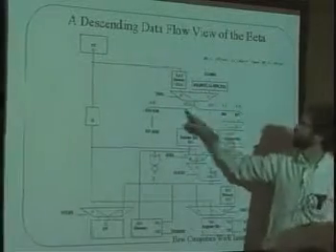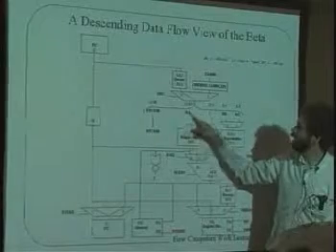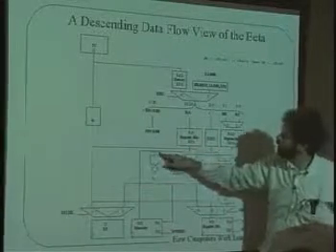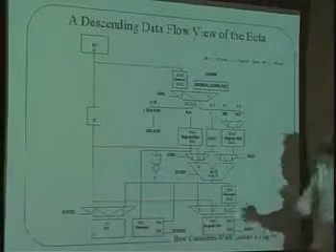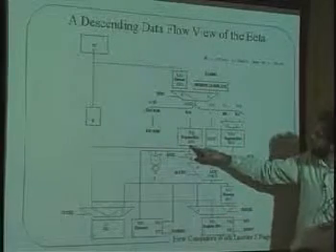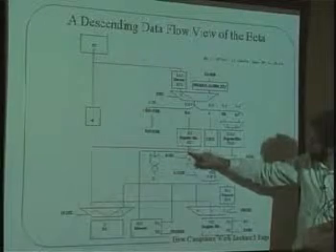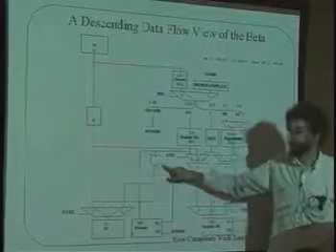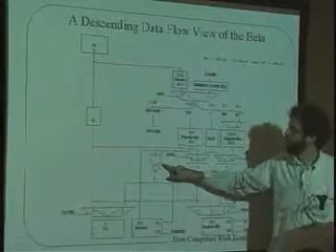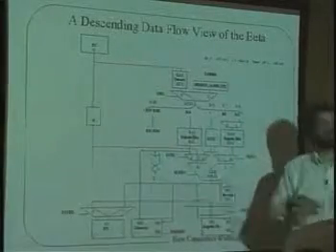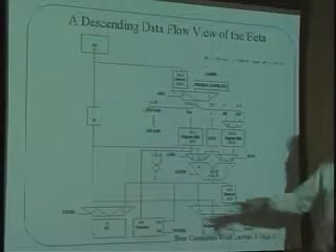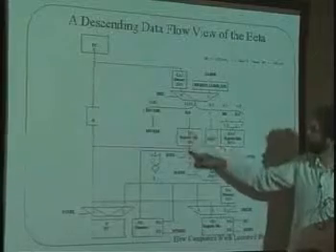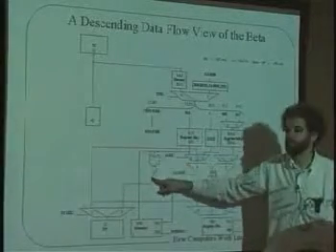The register that we choose to be register A comes out here and gets read here, and unfortunately I didn't make this read by last night, but the contents of register A comes out here and goes into this gate here, which we're going to talk about in the next class, which is a gate to test whether or not the data there is 0. And that comes out as Z here. Is it 0? And so we're going to test the contents of register A like so.